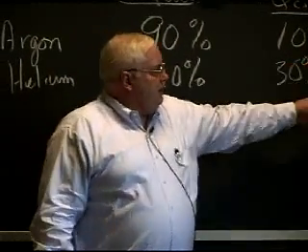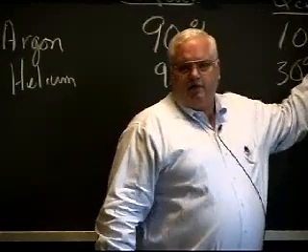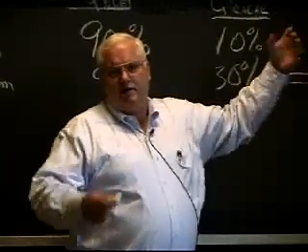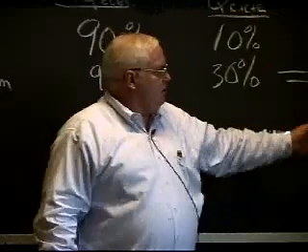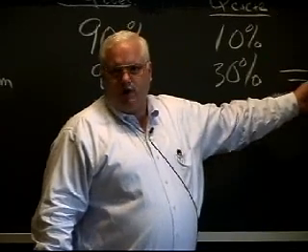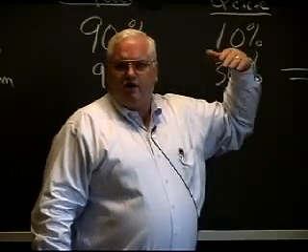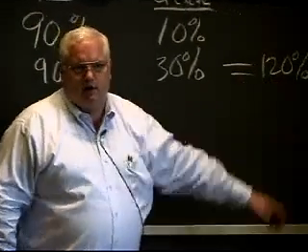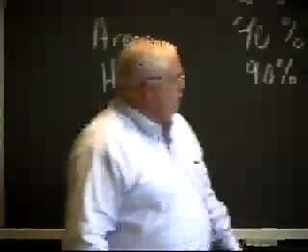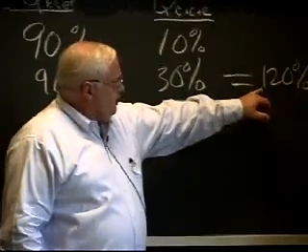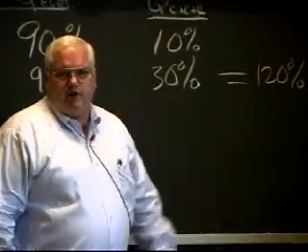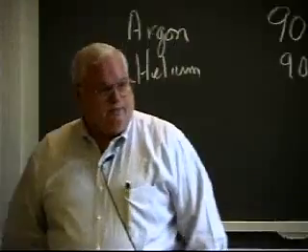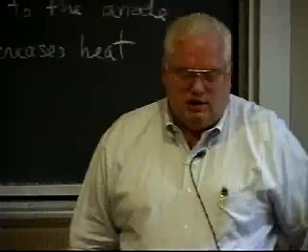If only 50% of the 100% in argon goes to melting metal and the other 50% goes into the heat affected zone, then going to 120% means I get 70% melting and 50% preheating the base material, for an equivalent arc and travel speed and everything else. That means I get a 40% increase in the volume melted. A 20% addition to 50% is an overall improvement of 40%.